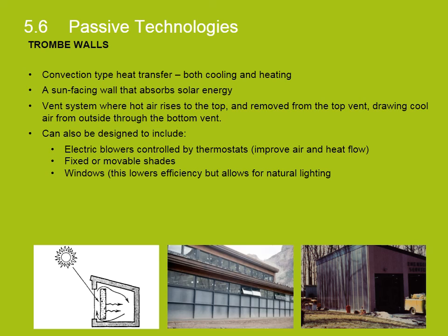Other features can be added to Trombe walls. Nowadays, electric blowers controlled by thermostats are incorporated to improve air and heat flow. Some have fixed or movable shades, while others have windows installed. Windows reduce the efficiency, but do allow for natural lighting to enter the space.